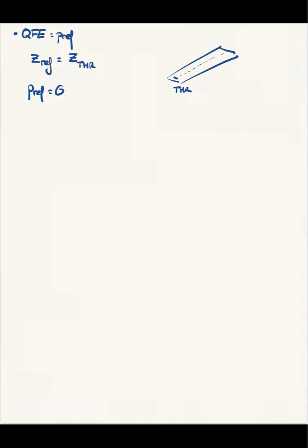Good. We may also introduce QFE on the altimeter as Pref. QFE stands for the static pressure at a given point on the surface of the Earth, typically a runway threshold. So if the surface of reference equals a given point, for instance, a threshold of a runway, then Pref equals QFE, and we are getting as a readout the height of the aircraft above this threshold.